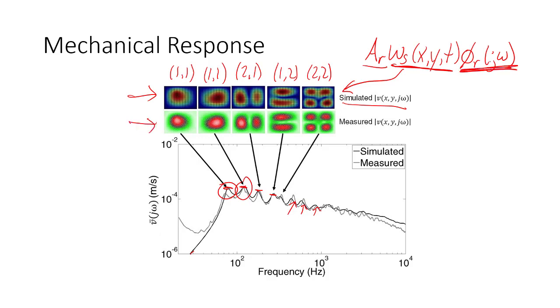The phi sub r of j omegas are the frequency responses of each mode. These are going to look like this. And what you've calculated and what you have to calculate in the homework are the resonant frequencies, which is the location of the peak of each mode. So obviously there's a lot more analysis that you can do than just calculating the resonant frequency.